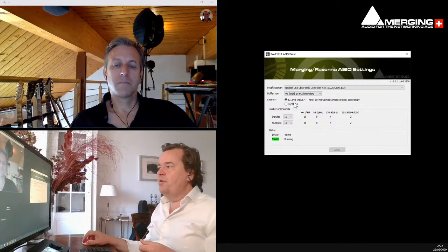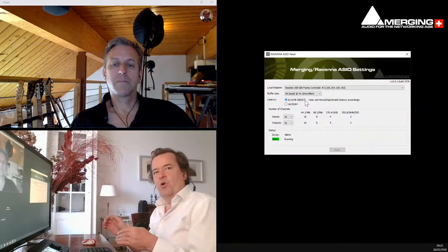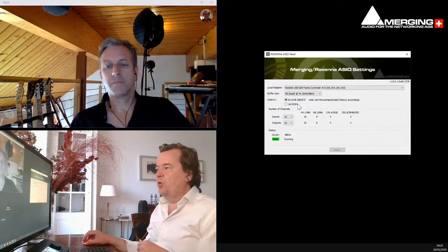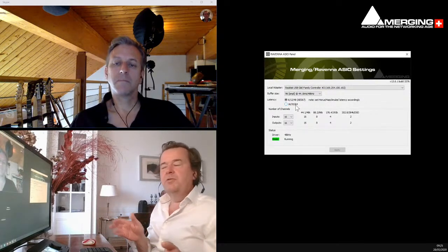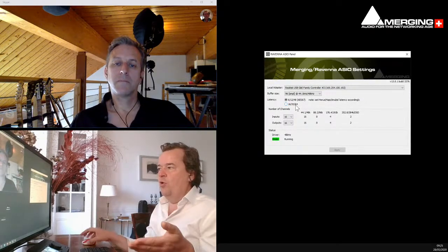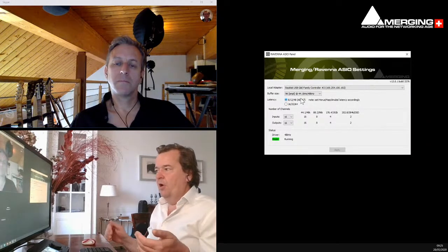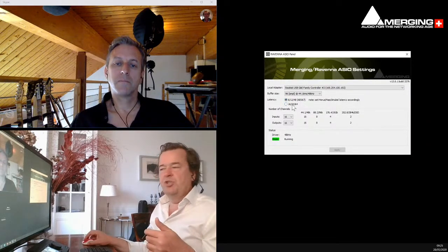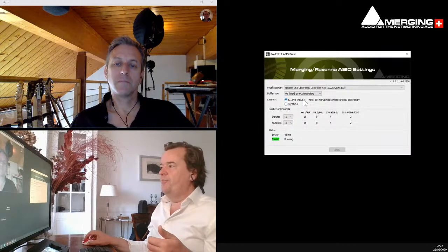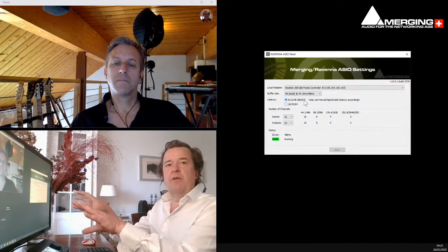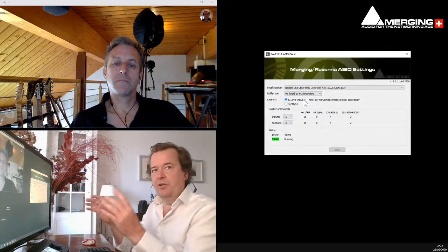So if you put one device here in AES67, which is either 6, 12, or 48 samples, and you put other devices here in 16, 32, 64, this will not work. So you either have to decide to go onto AES67, like here, or to go onto the other one, which is actually Ravenna. Now, once you install it, this comes by default. I kept my driver with the default installation, so you don't have to think about it.